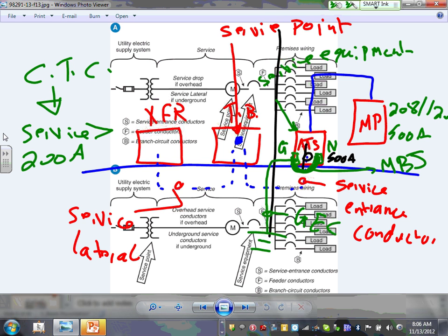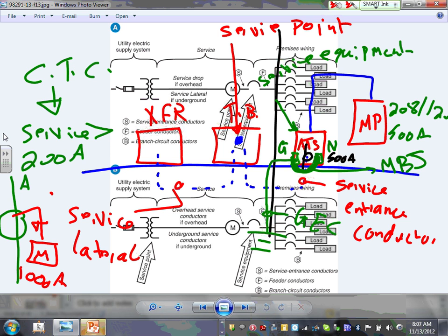they take that 1,000 amp and convert it to 5 amps. Do you know what the CT cabinet does? If here's phase A, there is a donut. Suppose phase A had 1,000 amp here. It will take the 1,000 amp and bring it to the meter, but it will be seen inside the meter as 5 amps. So every 1,000 amp will be seen inside the meter as 5 amps. Your meter is actually seeing 5 amps only, maximum.